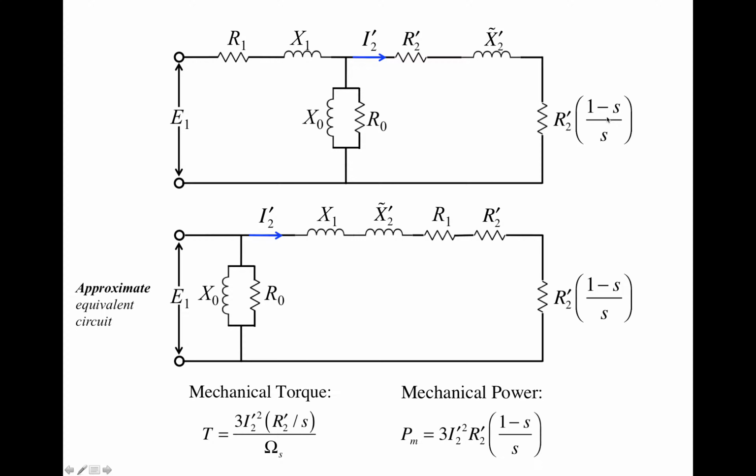If the induction machine is working as a generator, then the electrical power dissipated on this fictitious resistor is actually negative. It's dissipating a negative amount of power, right? Which means that the mechanical power is actually delivered from the load into the electrical circuit, right?